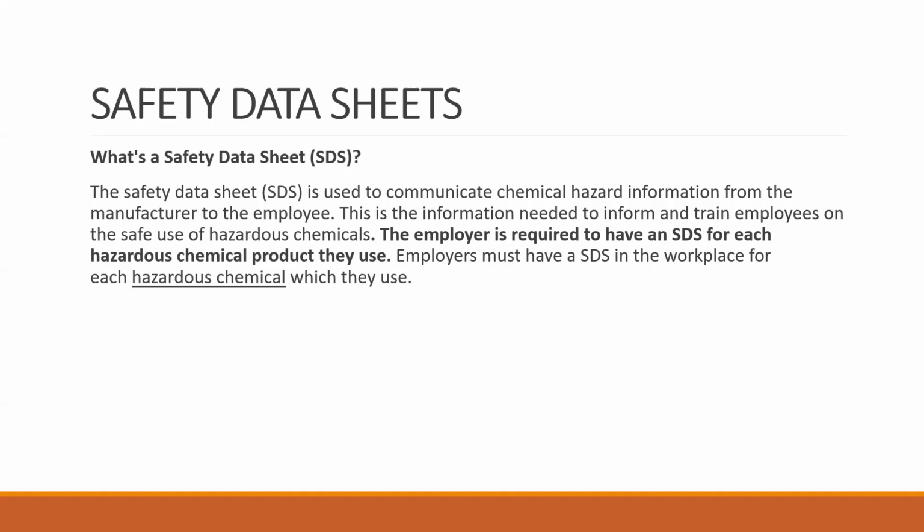From my experience, the thumb rule for the material safety data sheet is that it should be available at the point of use. When we say point of use, it means that where you are going to use this chemical, your MSDS should be available.